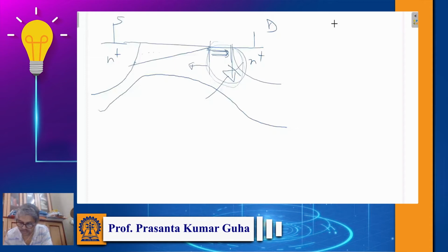The current will increase up to when it reaches the pinch off. So it is like a reverse bias diode in this particular depletion region. It is like a PN junction diode in reverse bias, and in reverse bias current doesn't increase. This is also true in case of BJT.